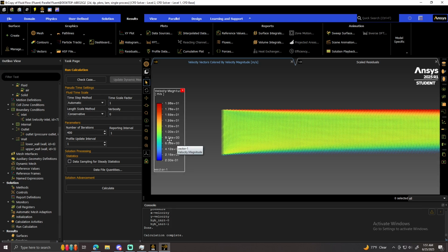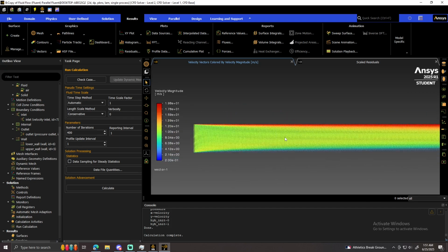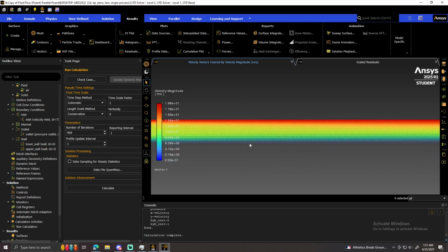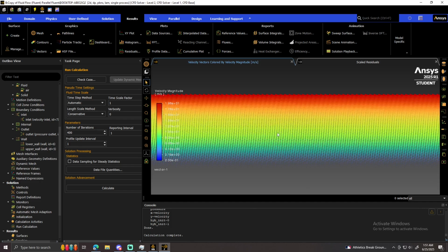So for us, in our case, it would be like 8.2 or 7.8 around there, which would totally mess up the volume flow rate, and then that would just mess up calculations. But either way, this looks good. This is exactly what I was hoping for. By this point, it's pretty much fully developed, and you can see a nice linear pattern right here.